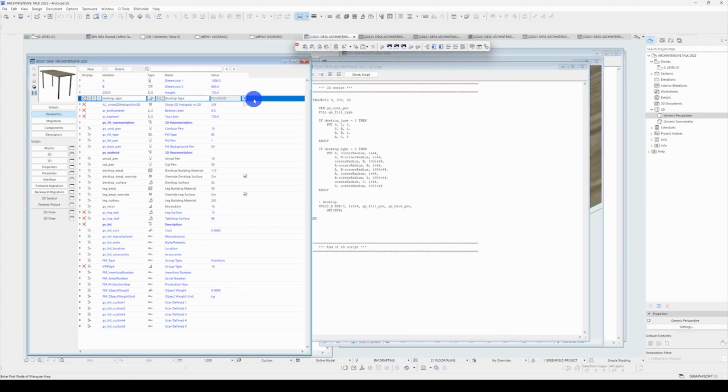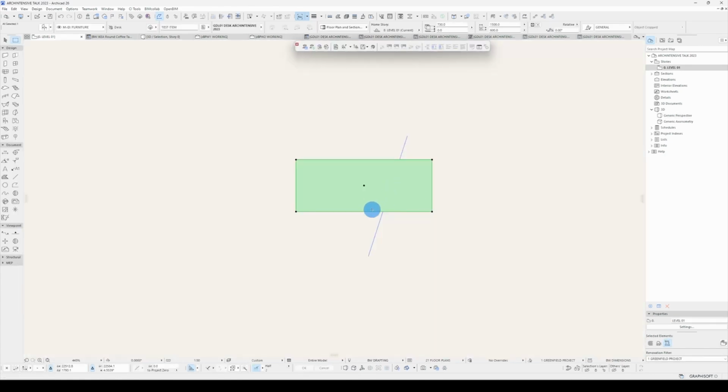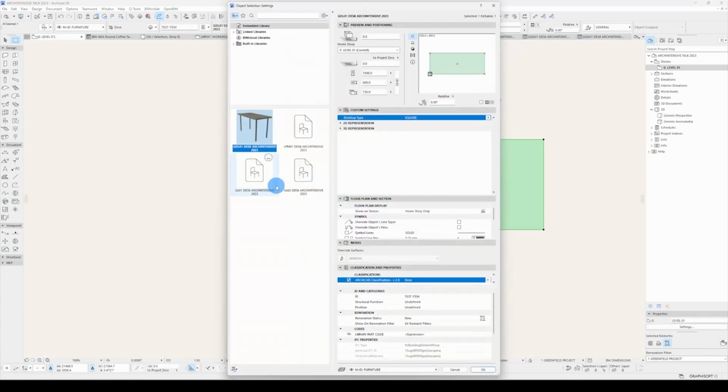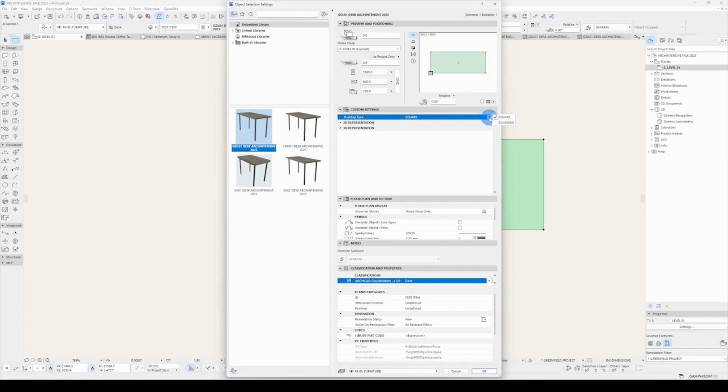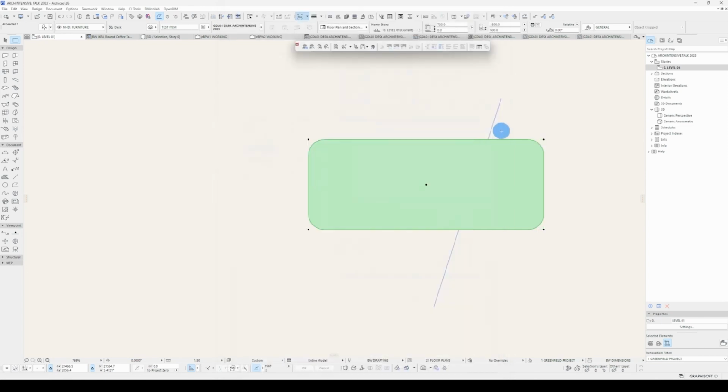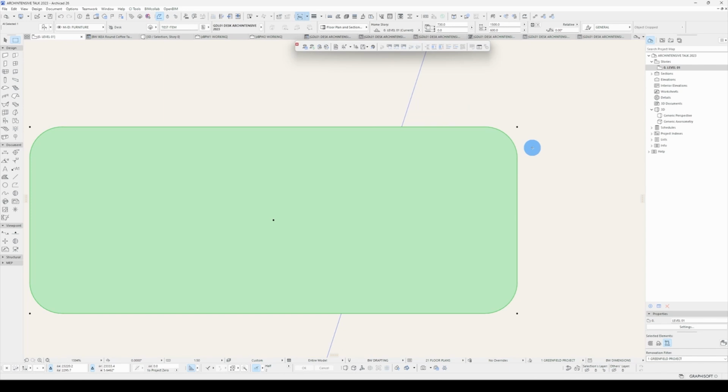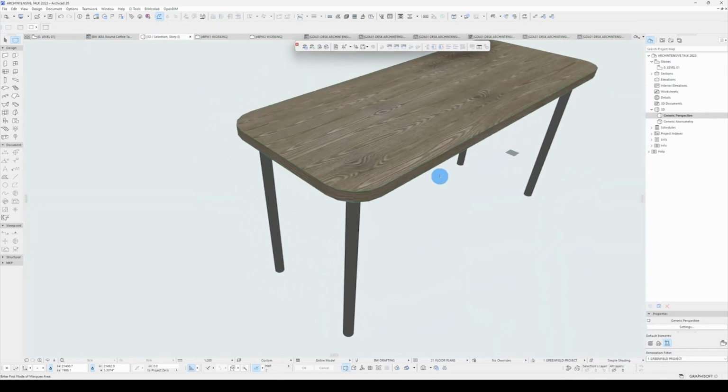Set my default back to square. Save the object. And we're done. Let's test the selection in the Archicad environment, and it's updated. It's kept its true shape, hasn't stretched, hasn't scaled. It's only changed what I've asked it to change.